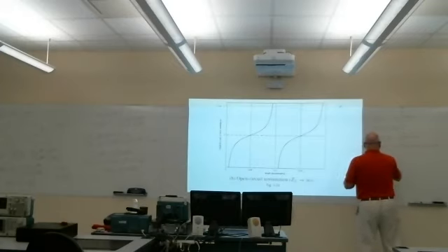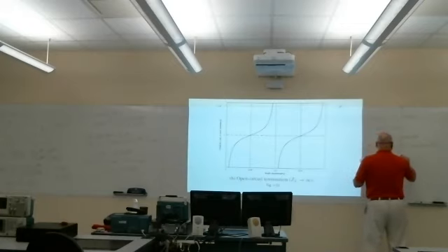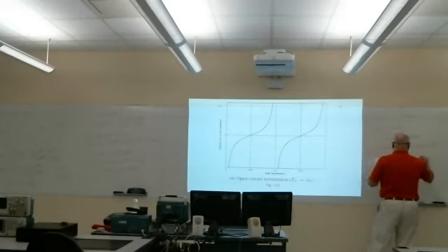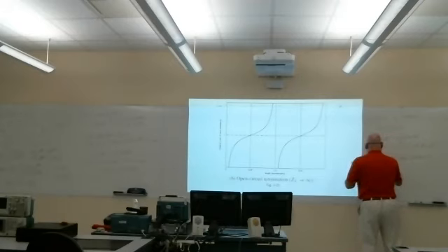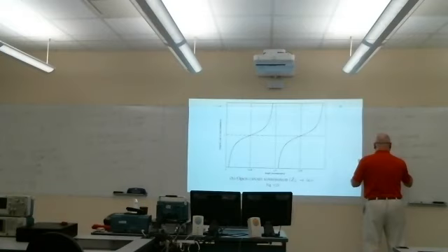So Zn looks like an inductor in the range where L is between 0 and lambda over 4.